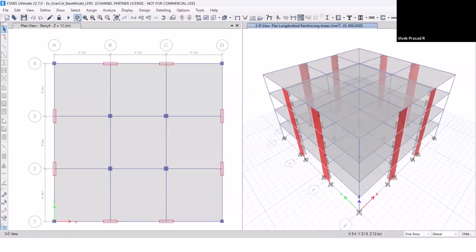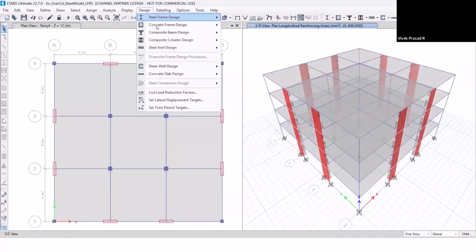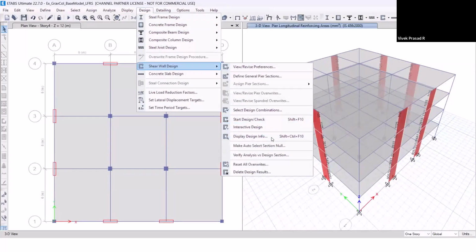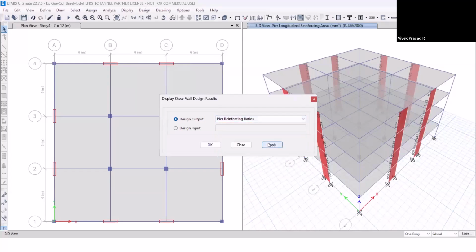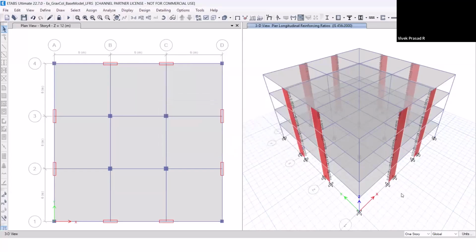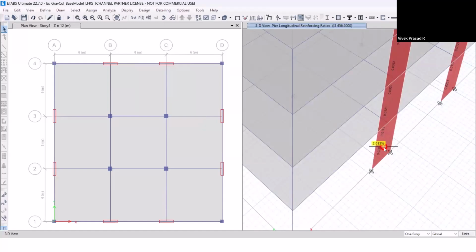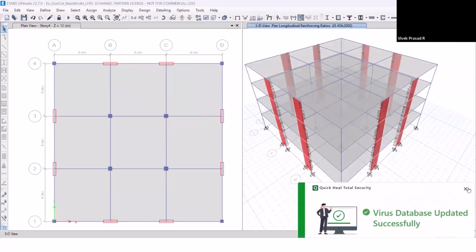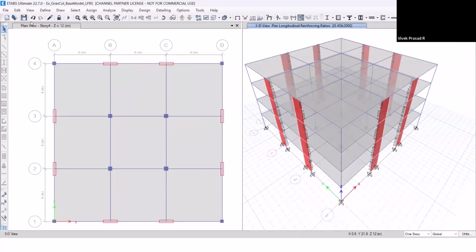Right. Now here you will see the walls are safe, and then we note down the reinforcing ratios, approximately 2%, 1.2, then 0.6, 0.25. So that's the variation. So at the base, importantly, it is about 2%, and this information is needed in the subsequent models.